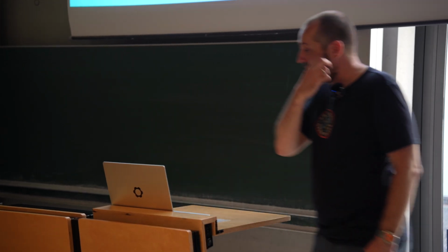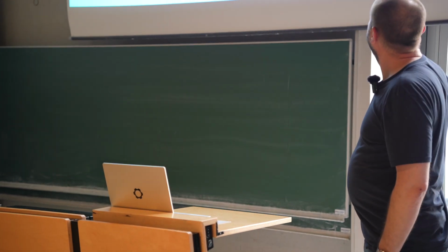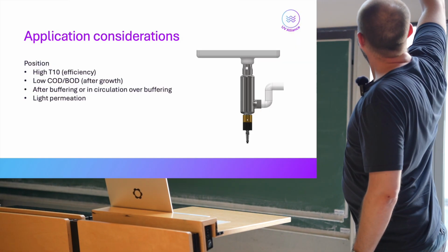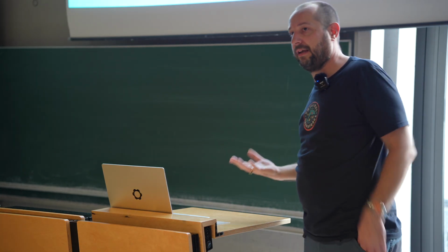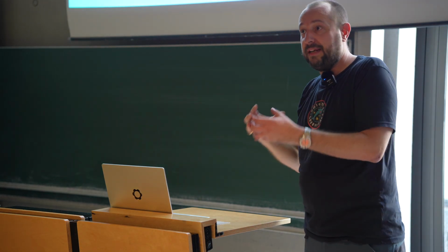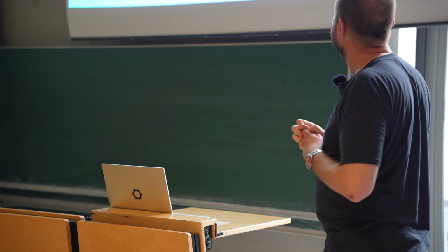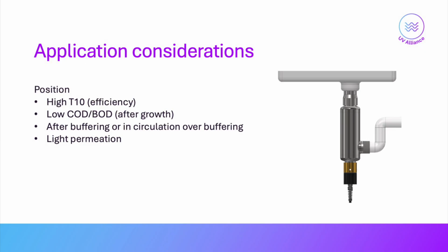Other application considerations are also important. This is a system we made to use under the sink in hospitals to avoid antibiotic resistance, to breathe in the siphon under the sink, which was a new application in a research project. And then you also have the other applications. You want to treat the water, but you also want to treat the air above it. Can your lamp handle that? Can your quartz sleeve handle those two areas?